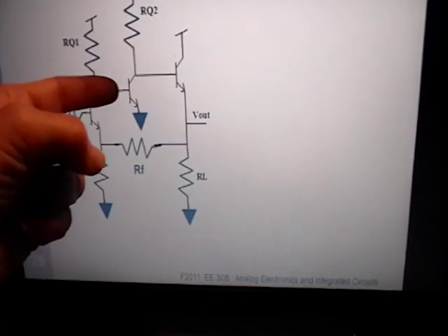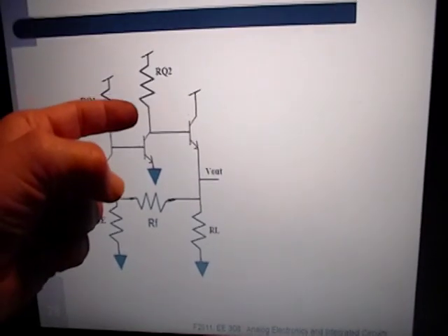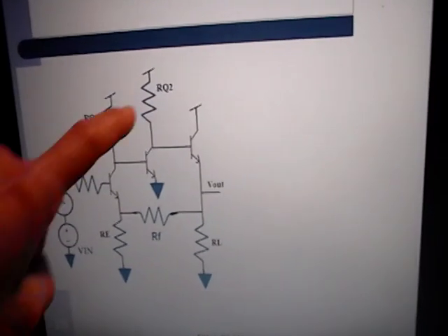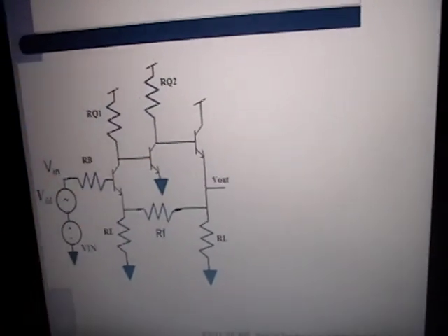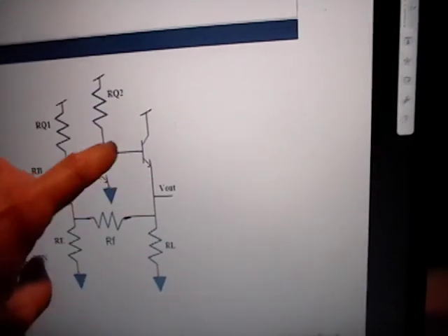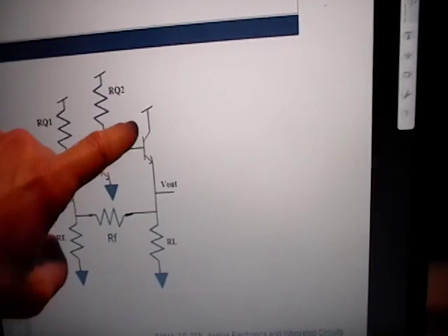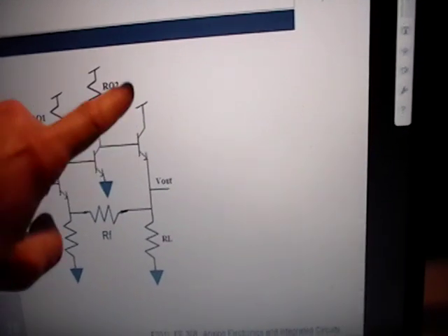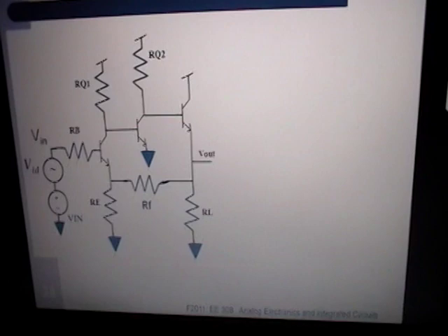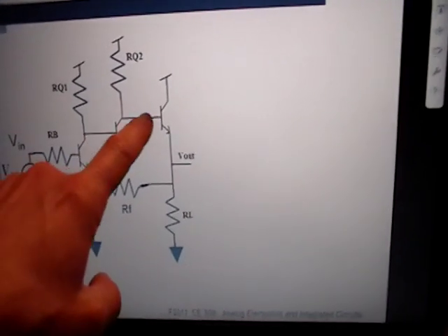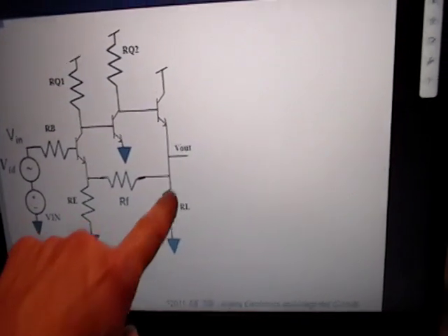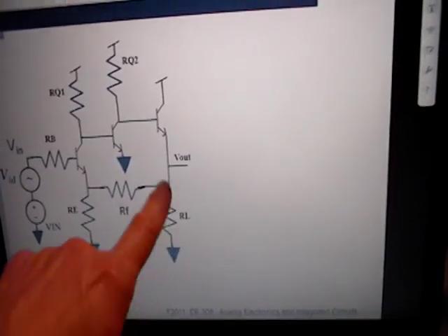Okay, now we come out of the output there. We look at this next amplifier. Okay, we have to do the vanilla thing again. And I see another common emitter. Alright, then we go over here and we look at this next stage. The output of this common emitter goes over here, goes into the base of this. First you have to identify what kind of amplifier that is. I see an emitter follower. And the emitter follower here, this resistor is absolutely necessary. It's not a follower unless it has either a transistor down here or a resistor.